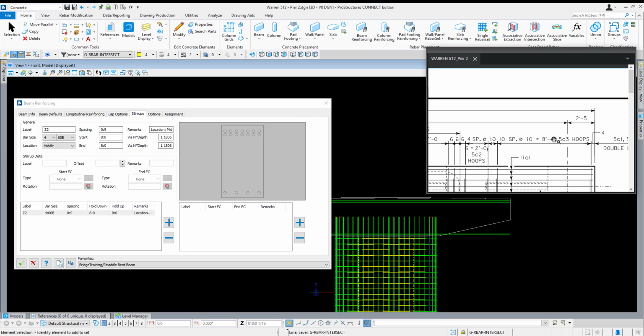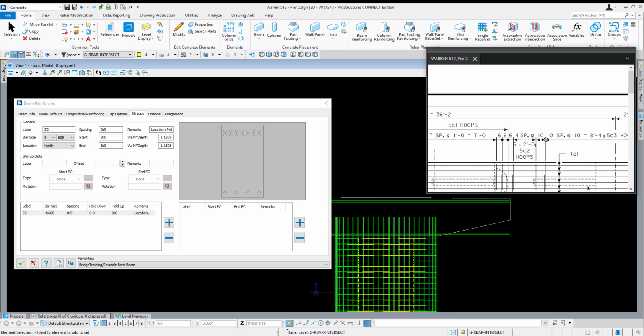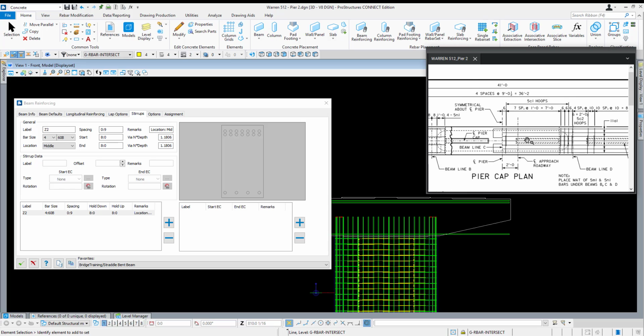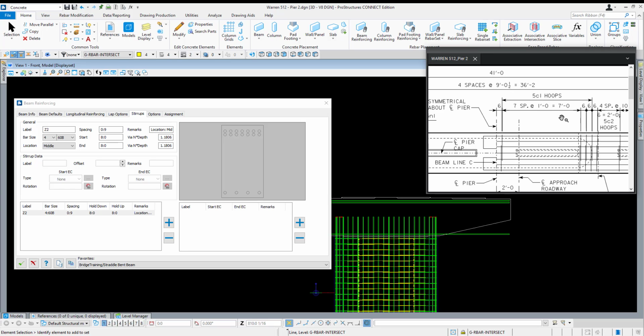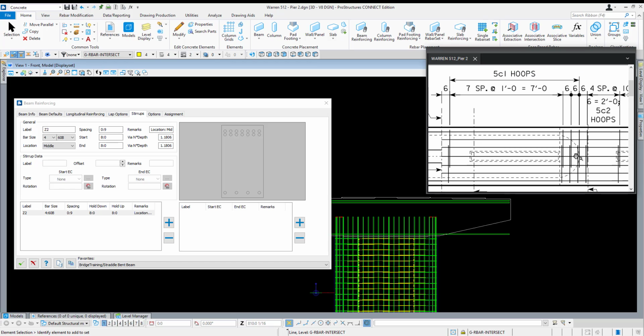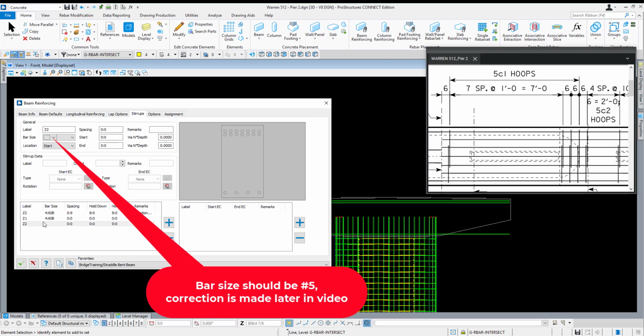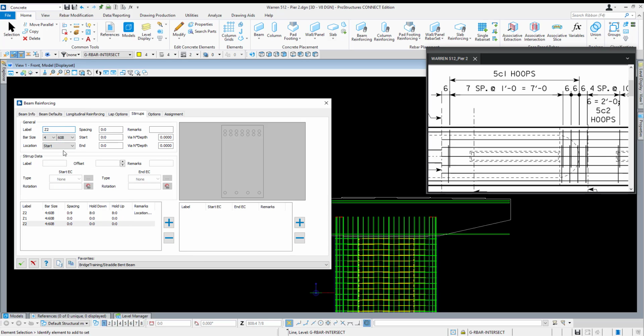Looks like we have a varied spacing. So predominantly in this area we're looking at about a 1 foot spacing. So that makes it easy. Maybe some additional 6-inch spacings towards the end. So yeah, we can go ahead and add and use that zone. We'll call it Z1 here and Z2. Bar size 4, and actually this will be Z3, I apologize.